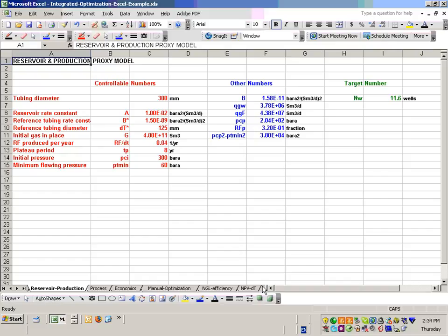And then what I'd like you to try to do is add a fuel consumption that is linear with the temperature. That you use up to 10% of the available gas as fuel if you're at minus 40 degrees C. If you're at 80 degrees, there's no fuel consumption. Just make it a linear function. So we add some fuel costs. So you basically just get rid of the sales gas. You just factor down the sales gas volume. You don't need to add a cost. It's lost revenue.